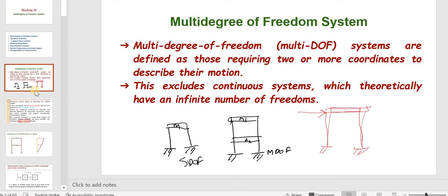That is, it will be similar to a cantilever. A cantilever is supported at one end, and then how will it be deflecting? It will be deflecting like this. Similar to that only, the structure will be deflecting. The whole mass of the structure is assumed to be concentrated at the horizontal level, that is, the beam level. So that is the meaning of a shear building model.